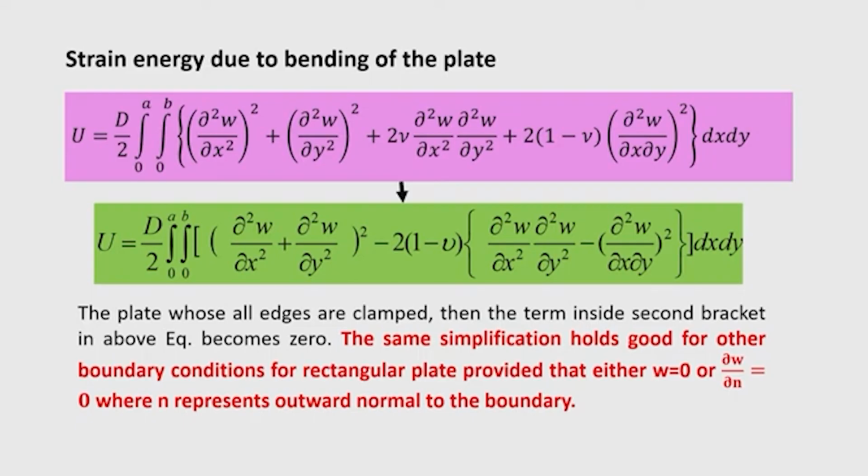Now, you are familiar with this plate problem, with Navier's method for a rectangular plate. So, if you take a Navier series, for example, you take the first term, w is equal to a sin pi x by a into sin pi y by b. Then substituting their second derivatives here, multiplying them, and subtracting the twist derivative square, the twist curvature, from this quantity, you will get 0.